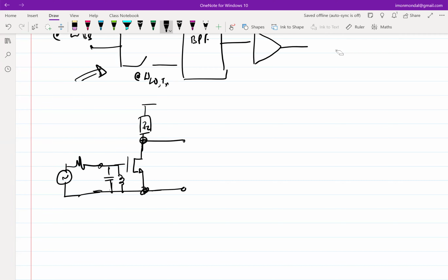Just think of a common source amplifier the way we treat it. It's a capacitive input resistance, so it never consumes any power at the input side. At the output, I get power, which means I have infinite power gain, always. That is not true. In the truest sense, at very low frequency, it's maybe okay. At high frequencies also, the way we model it, it's a capacitive input. A capacitor does not draw any power, so I should get infinite power. What I'm saying is, something is wrong with that model. What is wrong with that model?